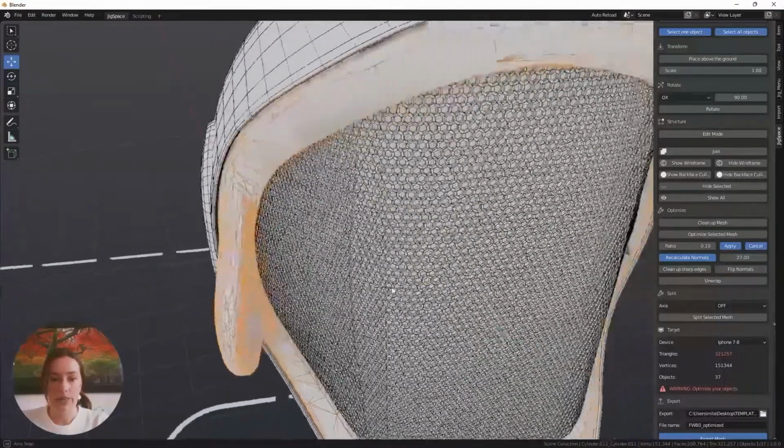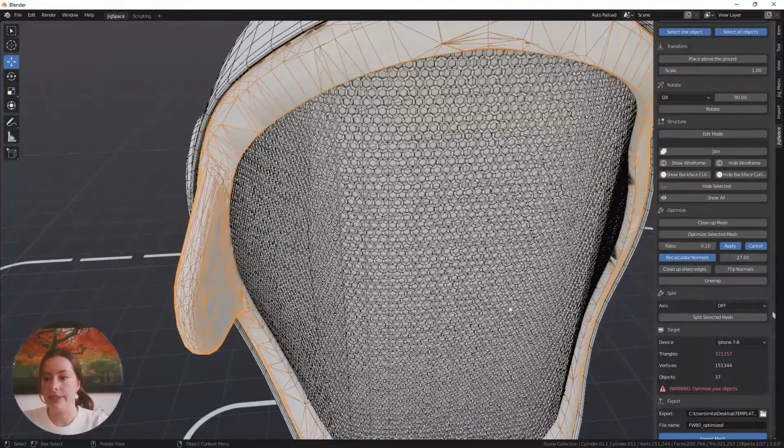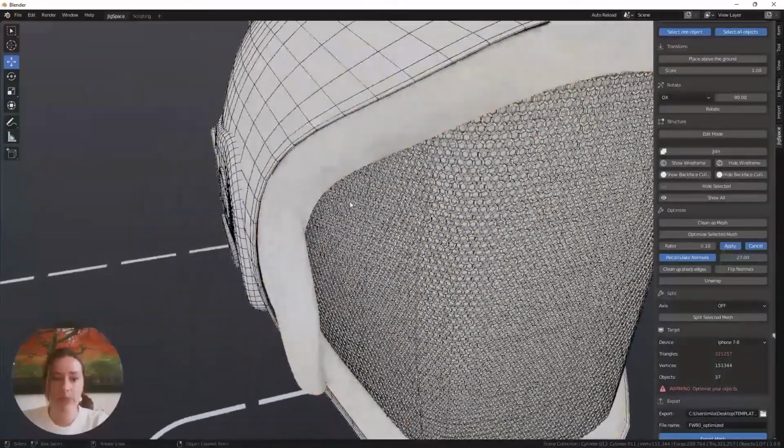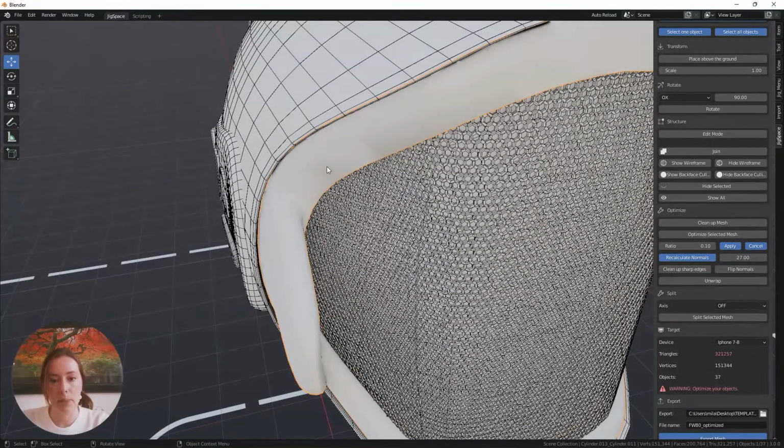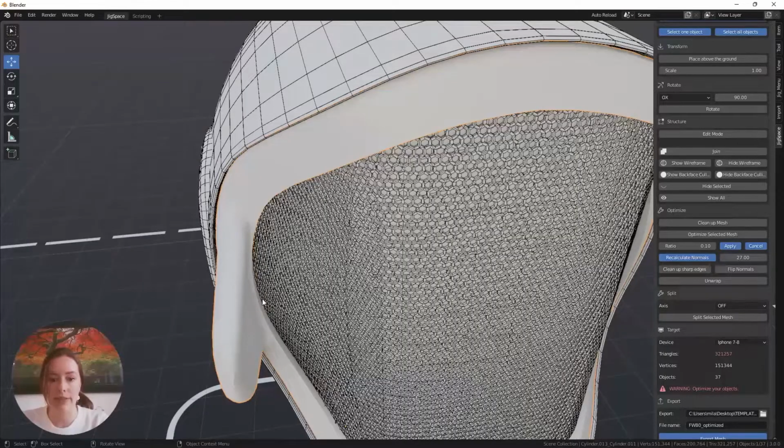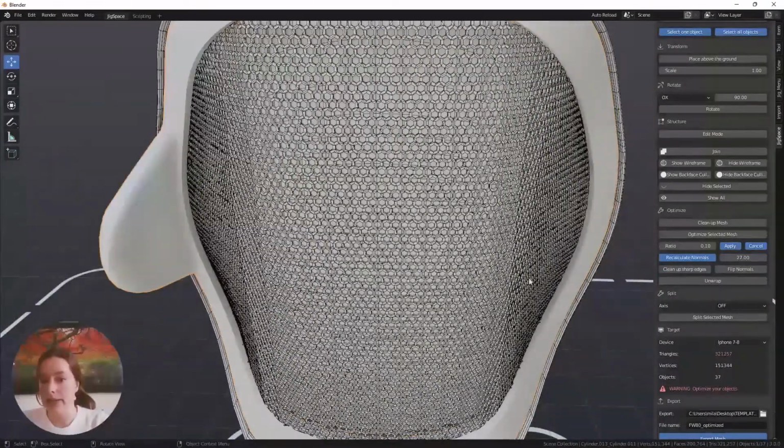Now, to look at the shape itself and the lighting that's affecting it, I'm going to hide this object's wireframe. And you can see here, we've got some creasing happening that's affecting the shadows of our object. So what I want to do is recalculate my normals. It's automatically set to 27, and I would generally recommend keeping it at that. So I've recalculated my normals, and despite this being at a ratio of 10% in the number of polygons it used to have, you can see that the overall shape hasn't really been affected.